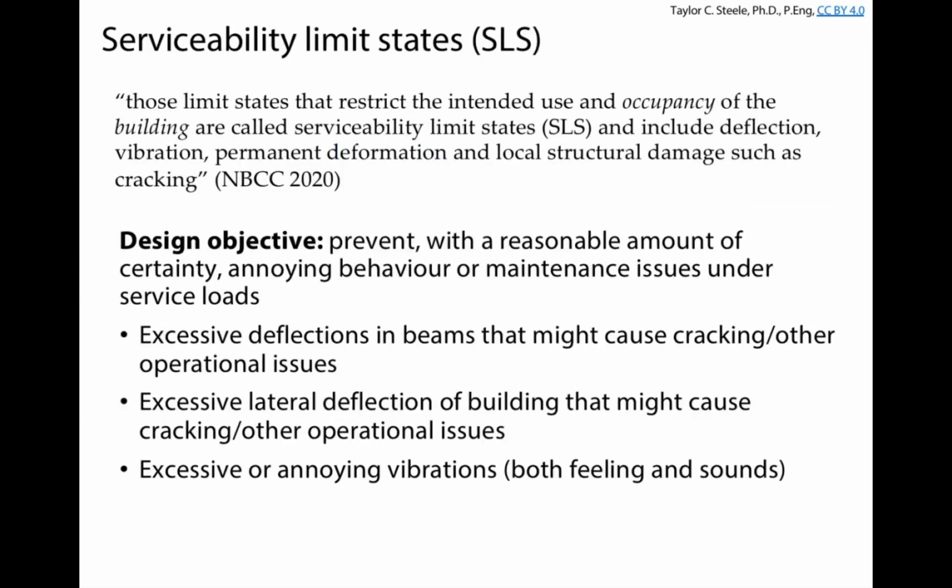What I want to talk about briefly before we wrap things up is serviceability limit states. And basically, serviceability limit states are those that restrict the intended use and occupancy of the building. And they include deflection, excessive vibration, permanent settlement, usually in a kind of a differential settlement behavior, or local structural damage like cracking. Cracking of walls prevents doors and windows from opening. Excessive deflection of beams tends to delaminate floor tiles or crack floor systems, and bouncy floors are just annoying. We want to prevent those kinds of things from happening.